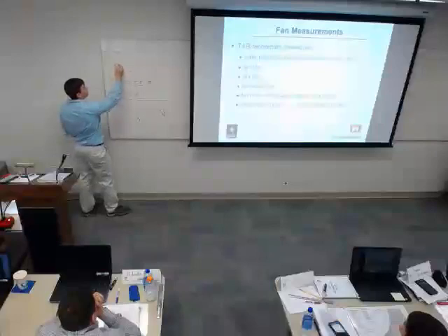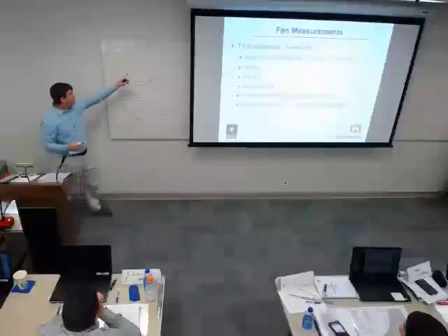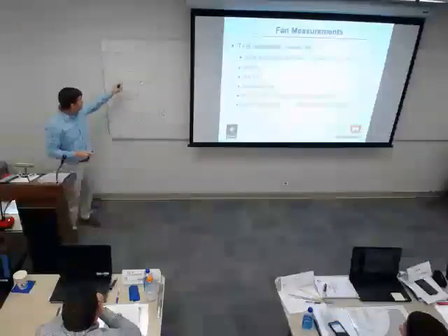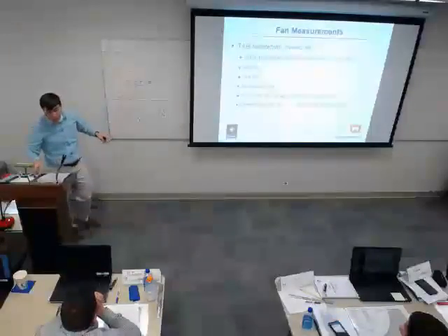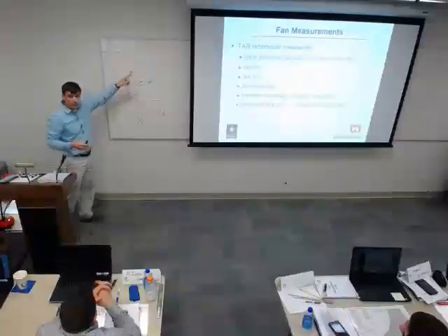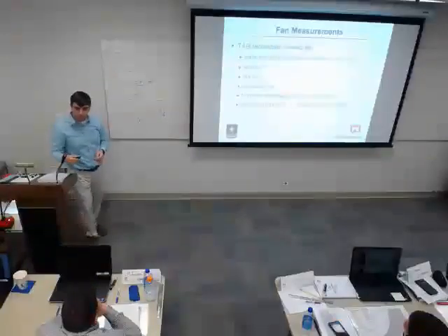If they're not the same size and I have a belt wrapped around the 2 pulleys, the fan can go a different speed than the motor can. So that's also how I would make a change if I needed to in belt drive fans. I can change the fan pulley and change how fast the fan is spinning. That make sense?